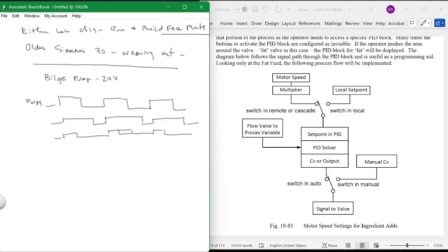You want to verify that the signal is there. So you start up in manual. You turn this valve to a certain position. You want to see a certain feedback coming back, and that's how you get started up. But why would we ever go to manual after we've started it up in the original position?